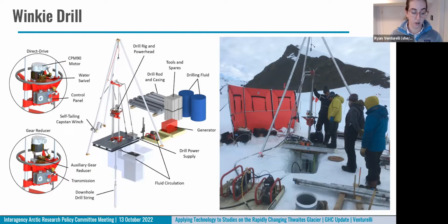It uses conventional rotary coring techniques common throughout mineral exploration, and a drill string of jointed pipes that can be advanced through the access hole into the glacier and collect bedrock samples below. We use bit cooling and chip transport with forward circulation, and it employs conventional coring rather than wireline coring.